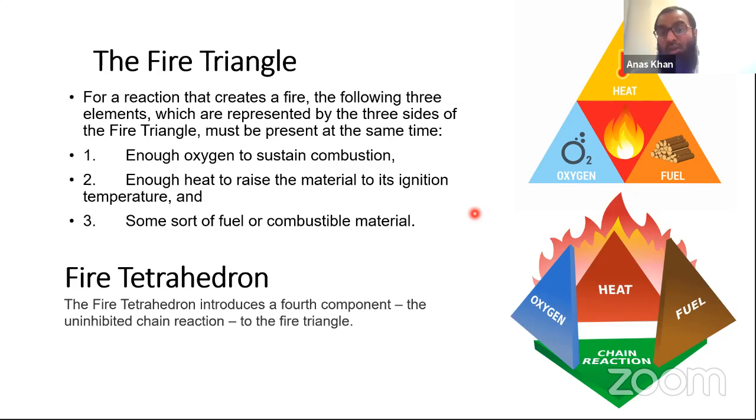Your cars or vehicles should have a spark arrestor available, because any unburned carbon can come in contact with any part of the refinery, where there is a lot of vapor all the time. That's why even welding is not allowed in the premises of the refinery. They will do the welding outside and then bring it in. And if any kind of smoke or ignition is very necessary, a hot permit is needed. For those working in oil and gas, it is a big challenge to get a hot permit in refineries or at oil and gas sites.